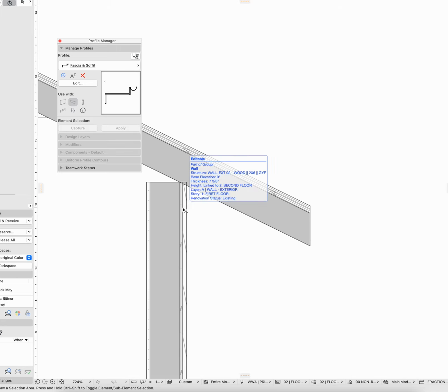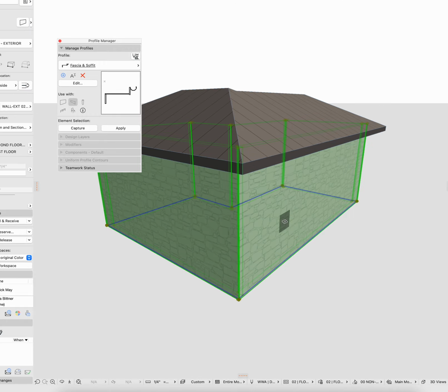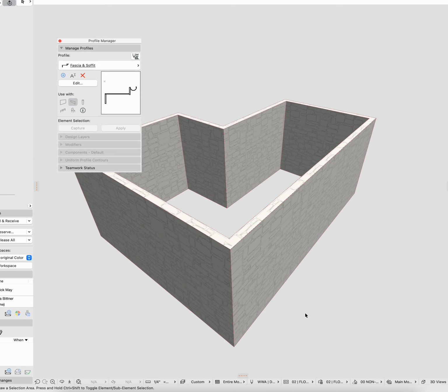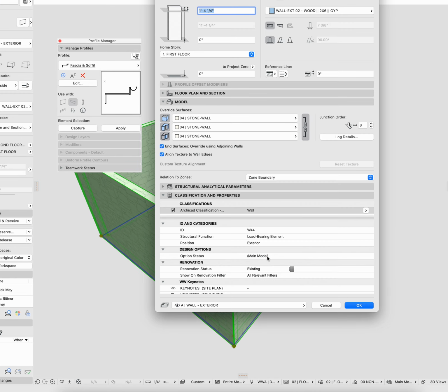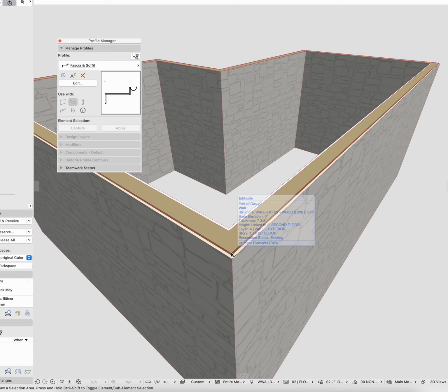Okay. Coming back into 3D here. Let me just grab all my walls and we'll say F4. Let's see here. What do we have? Oh, actually, it's probably in the wall settings. Yeah. So we'll just undo that. So now I can see the top plate right there. That's where I set my hotspot.